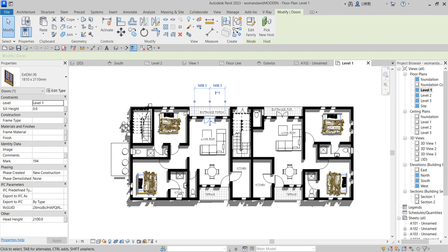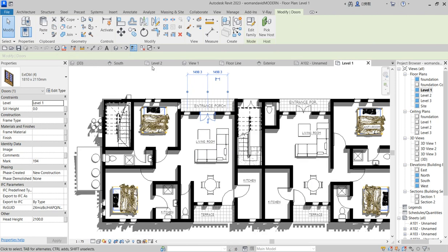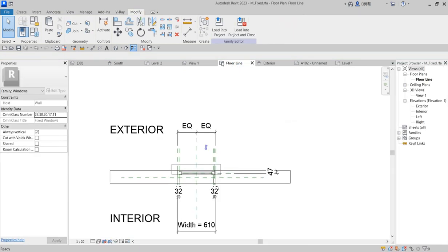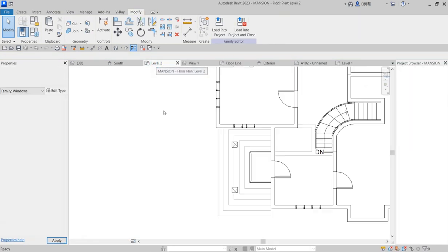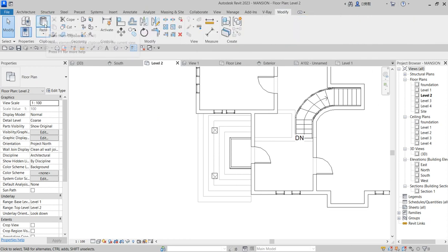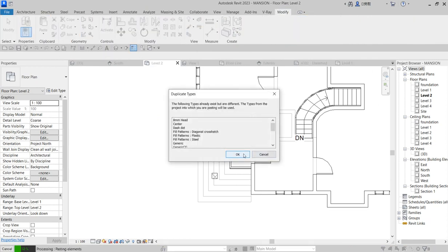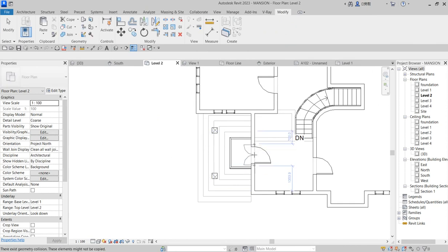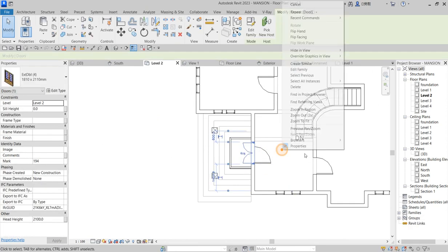So copy here to clipboard. I think I've taught you about this before. You copy an element from one page to another. So click on copy. You directly select that. So here on the floor plan, something like floor plan level 2, you can decide to say okay, component or modify. I say paste from clipboard. Say okay. You just drop it here.